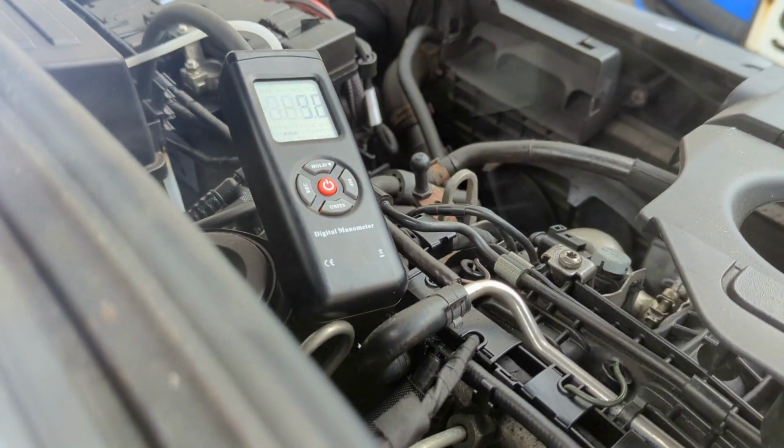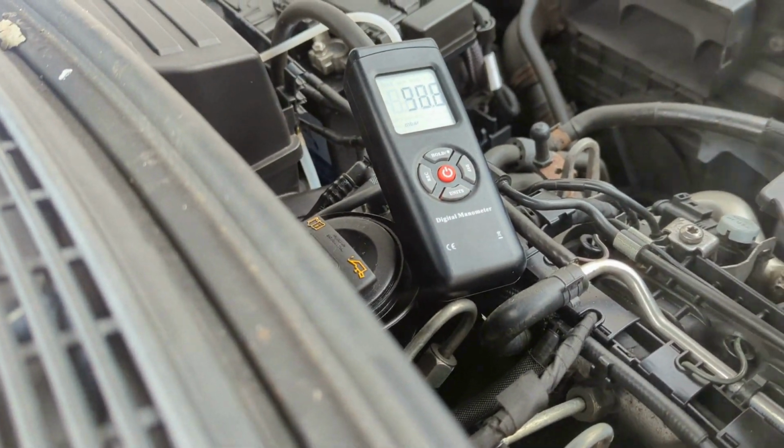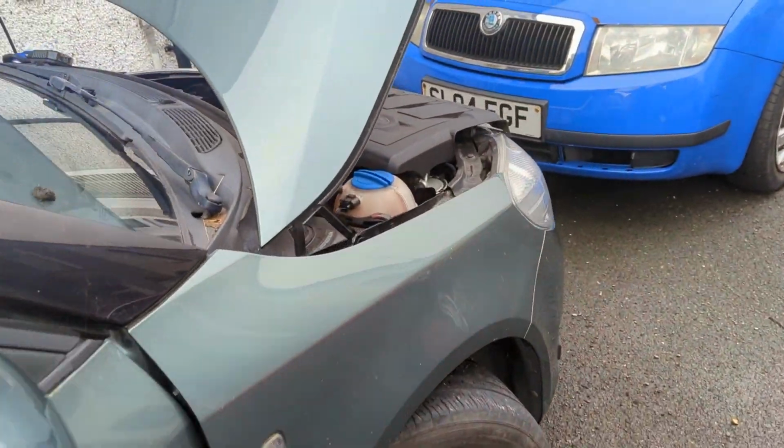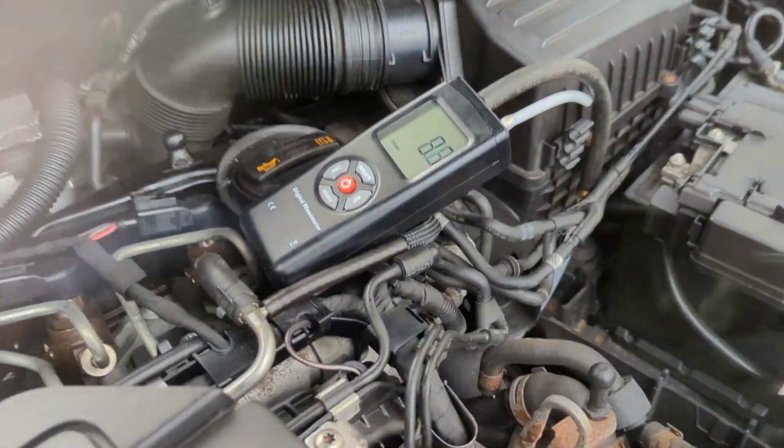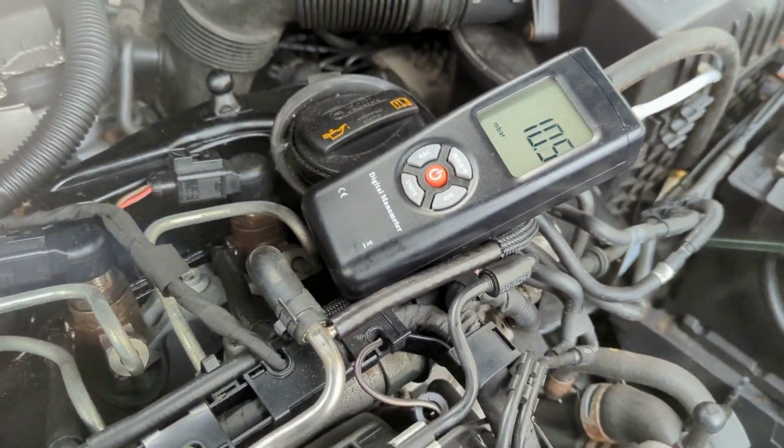Increase engine speed. Couldn't really see that. I think it went up to 50 roughly. I'll have to watch the footage back and have a look. Yeah, maxed out about 50ish, but it was 37, 45, so it's a bit higher than I would expect it to be, but it's not too high that it should be causing the boost issues that we've got. So I'm going to disregard them DPF codes for now, and we're going to move on to that turbo actuator code.